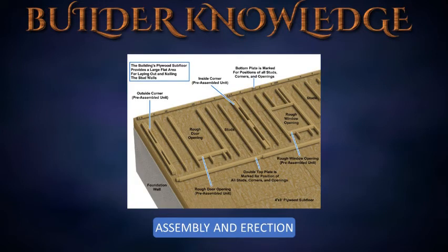Now we have all of the pieces ready to be placed. Nail the entire wall together while it lies on the subfloor. Position the top and bottom plates on the subfloor at a distance slightly greater than the length of the studs. Position the corner posts and rough openings between the plates according to the plate layout. Place the studs in position with the crown side up and nail the plates into the studs, cripple studs, and trimmer studs. Reminder, on long walls, breaks in the plates should occur over a stud or over the header.